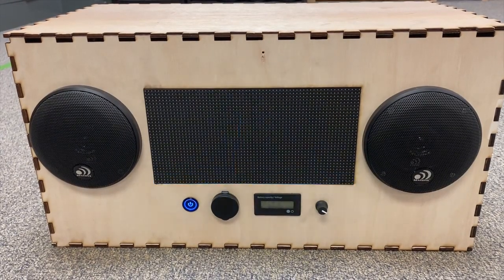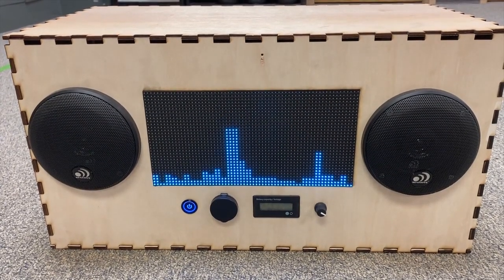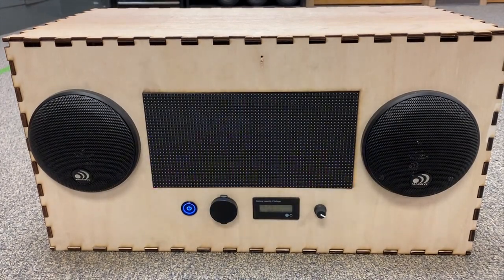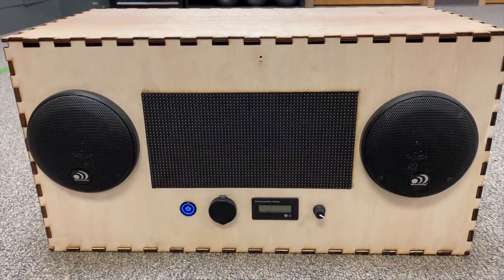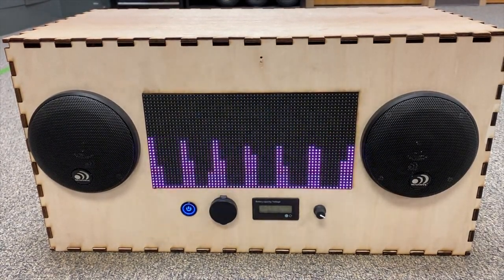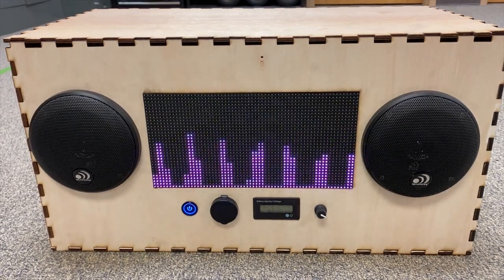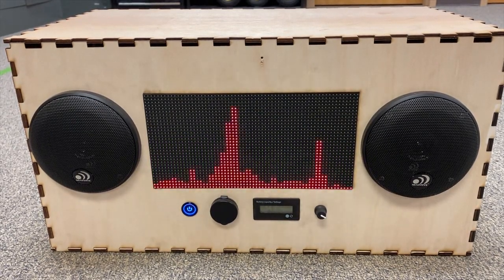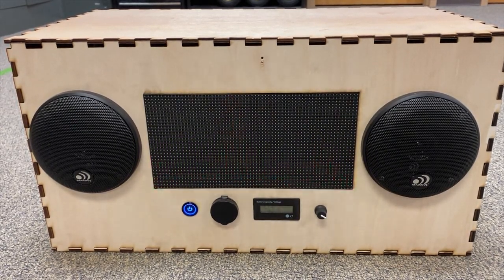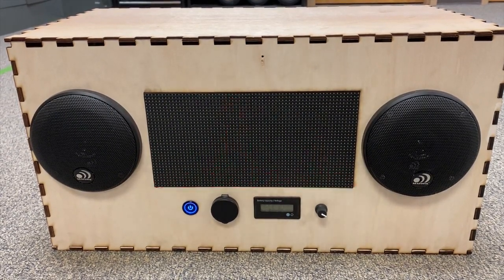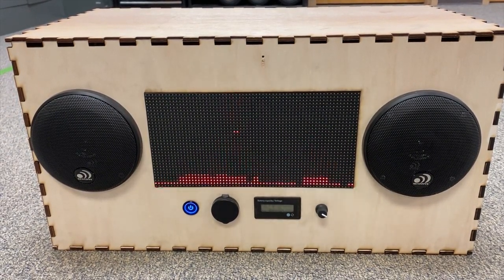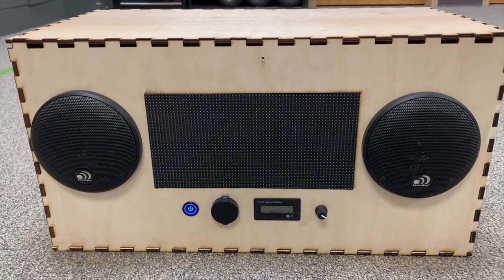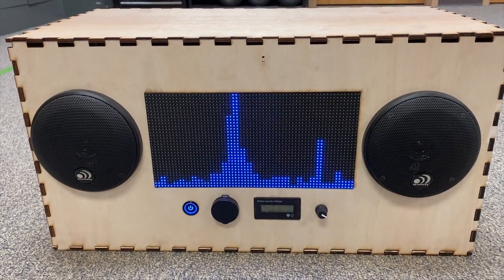This next representation is showing our different modes of fast Fourier transforms. So as you can see, there is a consistent frequency of 200 Hz being shown, and that is being shown in both the frequency domain and the time domain as shown here. The color and the rate of the Fourier transform can be shown. So the fast Fourier transform is without the averaging, whereas a slow Fourier transform includes the averaging we alluded to earlier.